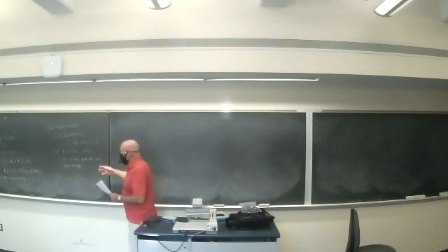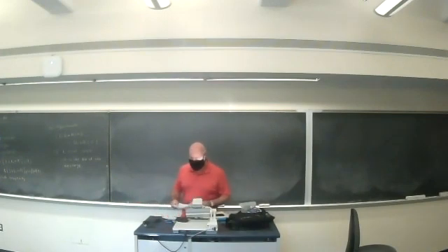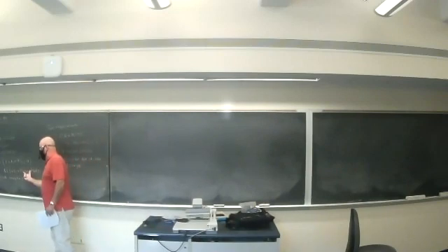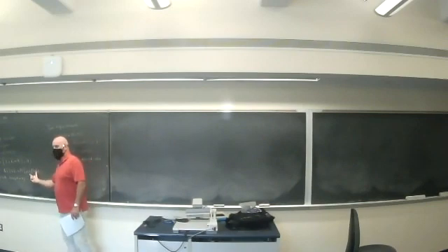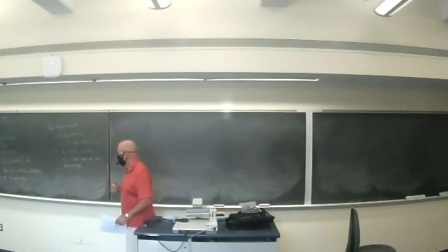But I want to try and draw some pictures here to give you an idea of what this looks like. We'll look at it in the time domain. It's important to have an understanding of it in the time domain, especially so that you understand how the AM receiver works. But then we'll also look at what's going on in the frequency domain. We know that multiplication in time becomes convolution in frequency, right? But fortunately, we're convolving with a cosine, which is an impulse in frequency, so the convolution is pretty simple.